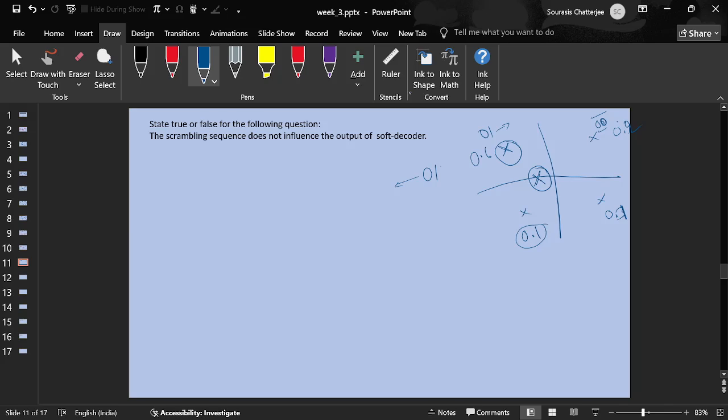So let's say in the context of hard decoding, if the receiver is observing some SNR at 100-meter distance from the base station, now if you employ soft decoding, it is going to observe the same SNR at 200-meter distance. Even if it looks small, it's actually a huge benefit that you are able to maintain the same level of SNR even if your distance is twice. So that is what soft decoding is. Soft decoding is not making a decision on its own, computing the ratios, the probabilities, and feeding those to the LDPC decoder.